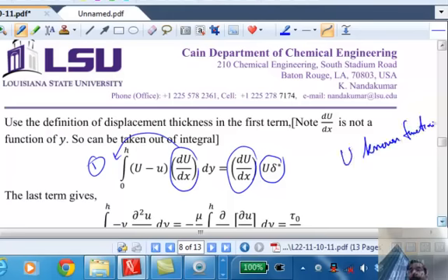How is it known? By solving the potential flow at the edge of the boundary layer. So that means whilst getting u, you can use the potential flow theory. Forget about the boundary layer. Take whatever shape of object that you have, solve for the potential flow, and evaluate it on the plate, that is going to be on the wall, and that is going to be your u, which will be changing with the wall length, along the arc length of the wall.